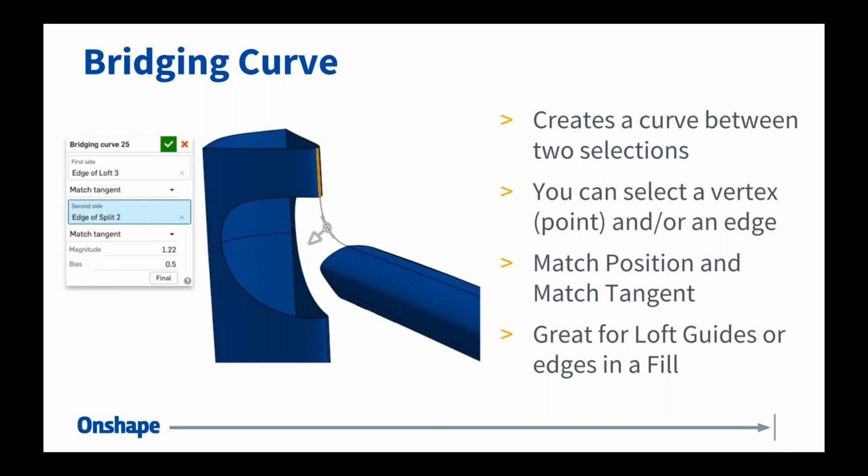profile. A question, conical helix. Yes, this was asked earlier. You would just simply use a conical shape, a conical solid to define your helix, right? Just select that face as your definition for your helix. If you stick around for the end of the webinar, I can model something up quickly here and give you an example.